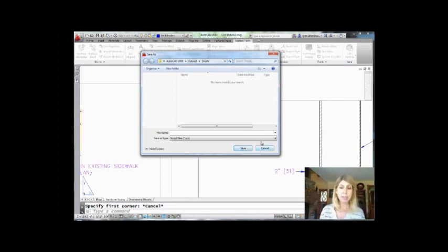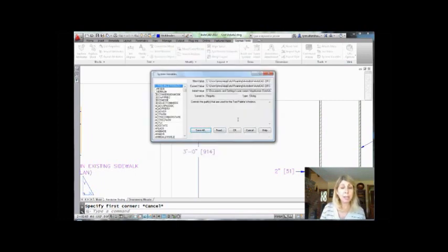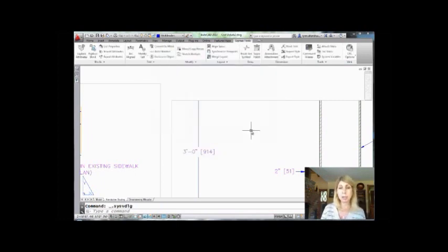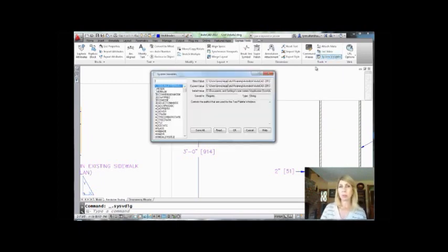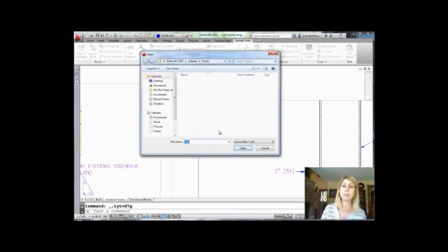All right, so let's say you saved it as an SVF file. We'll just pretend that we did save all our settings as an SVF file. It's in the wrong directory, but we're just going to pretend. All right, so then let's say we leave the dialog box, we go on our merry way, things go terribly wrong, and all of your system variables are all messed up. They're not set to what you want them to be set to. No problem. Just go right back into that same command and you use the read option. And there you'll see there's our saved file there of all of our system variables. We would read it back in. It would reset them all very quickly and very easily.